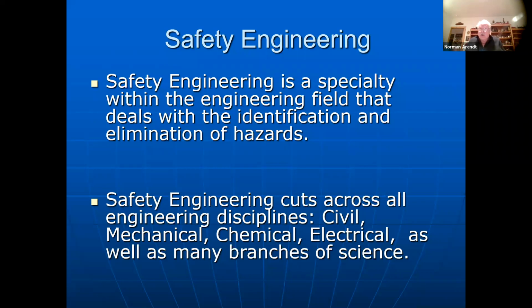You might be familiar with the term constructability. That refers to the idea of incorporating construction expertise into the design process to ensure that design is cost-effective and buildable. Designing for construction safety can be viewed as ensuring that constructability review includes the safety aspects of the project. It's important to note that when we talk about designing for construction safety concepts, this only applies to the design of the permanent facility, whatever that is, whether that's a road, a bridge, a building, you name it.